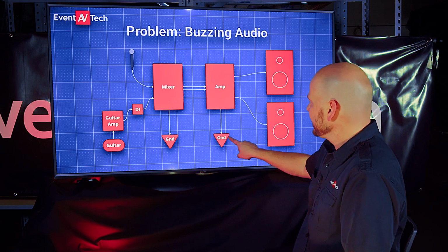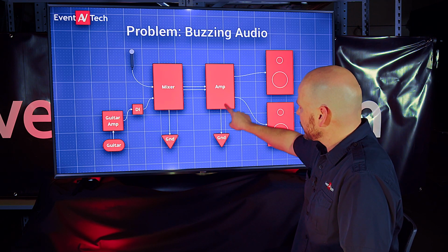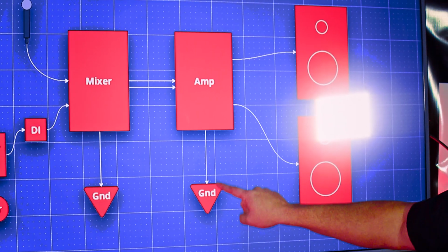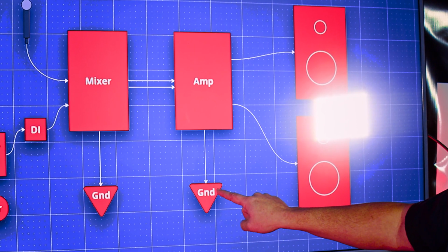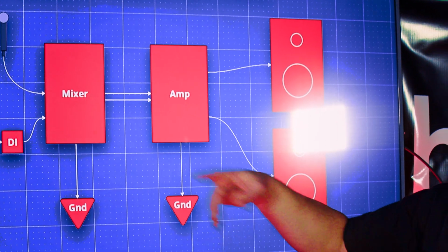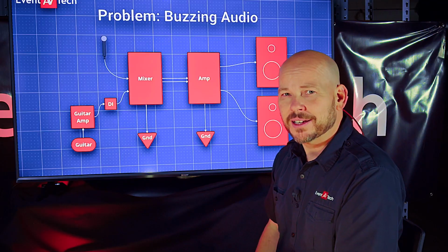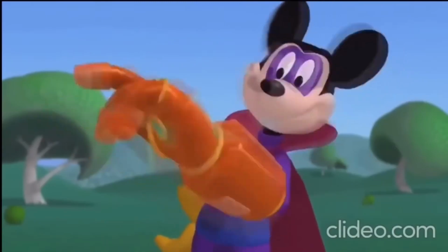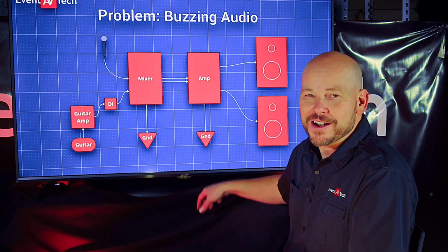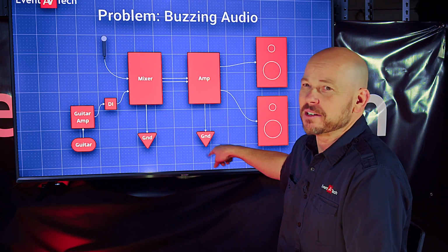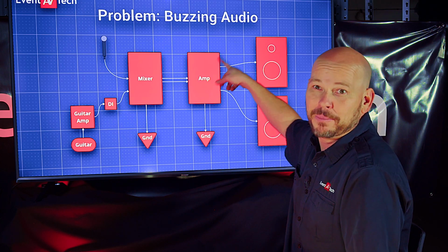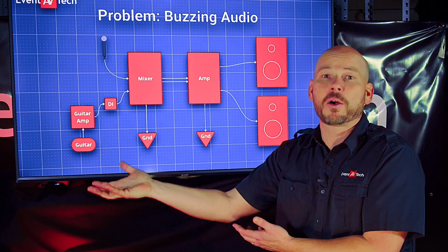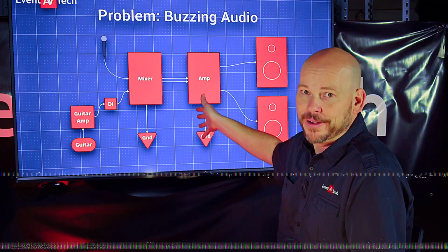Now, I will say, if on the power circuit that your amp is coming off of, somebody else in the building connected to the same ground has decided that they would like to make margaritas, and they've got a margarita machine just doing the cha-cha all over your power, when you disconnect this, that margarita machine's still gonna do the cha-cha and you're gonna get a buzz in your amp. And now you know you have a dirty power problem specific to your amplifier.